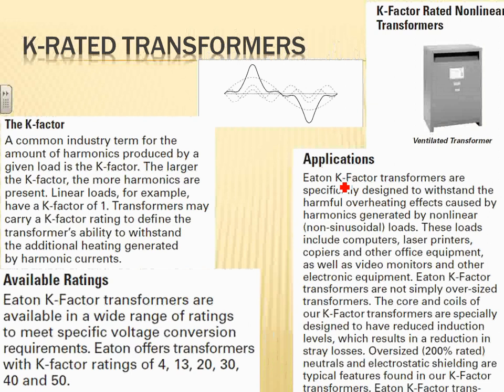So they have multiple harmonics. It adds up to a wave, and it's an ugly wave like this instead of a beautiful smooth sinusoidal wave like this one. So who cares about the wave? Your equipment will be overloaded and heated, the neutral and transformers. So you hear a lot about K-rated transformers. Remember these are delta-Y transformers, so you have a delta on this side, a Y on this side.